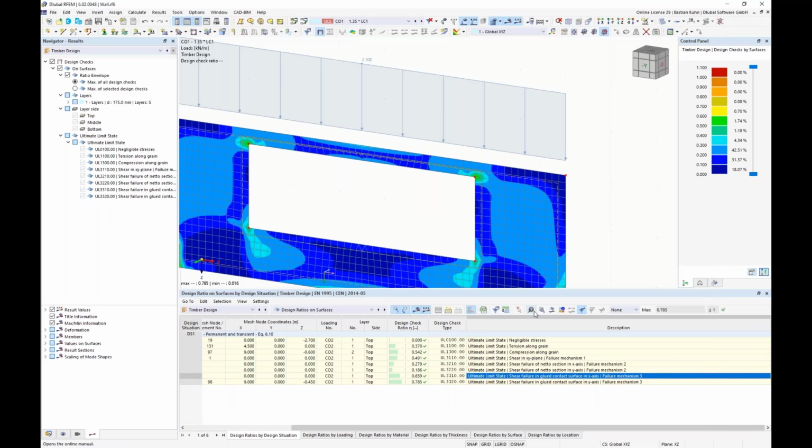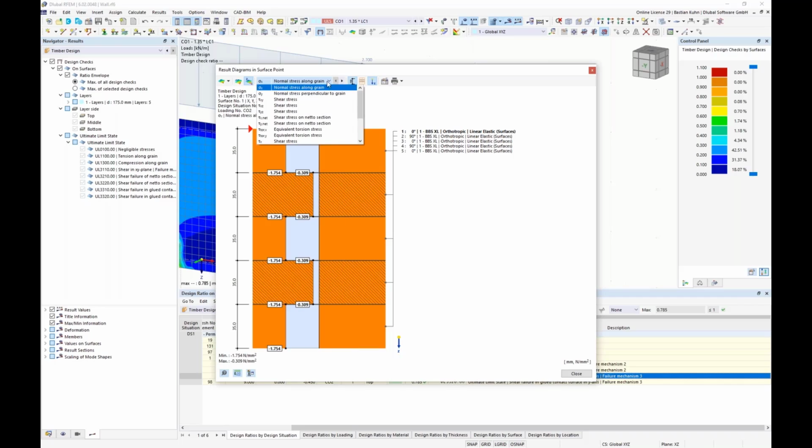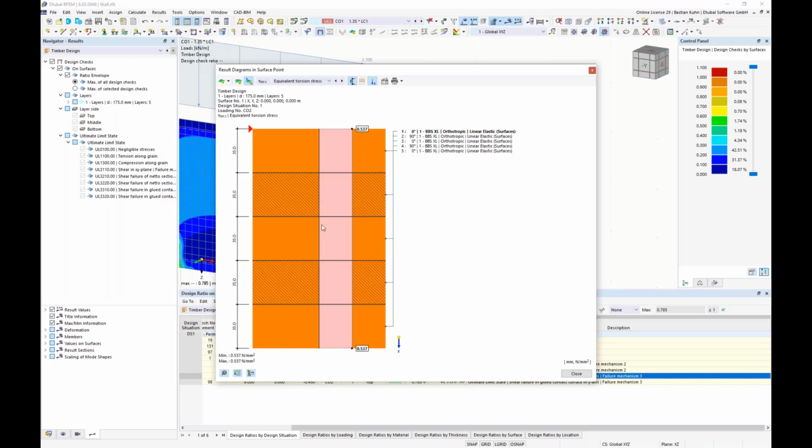So the basic point of it definitely is the stress of the torsion. Okay, tau X, that's here. Of course, it's constant over the whole section. That's always the case for this kind of stress. And here you have it in the net section, which is failure mode 2. Okay, good. To me, it all worked nicely, or quite well.